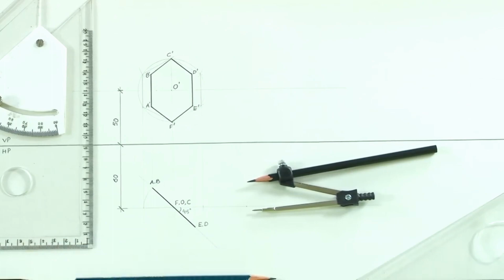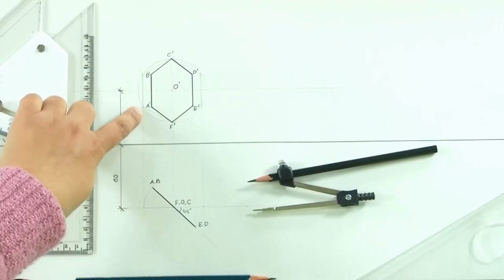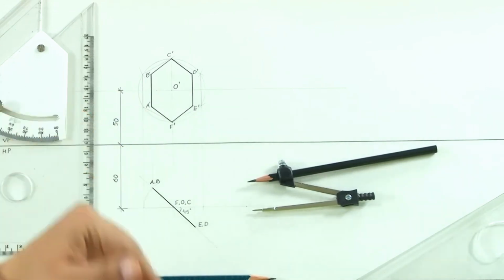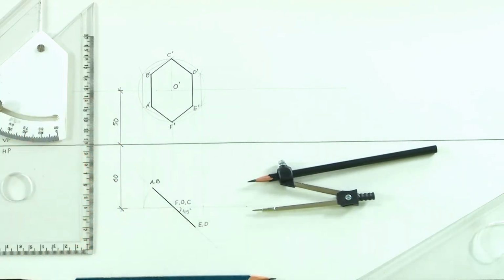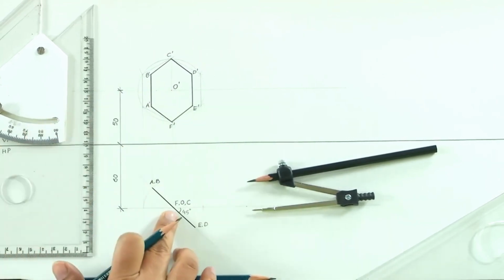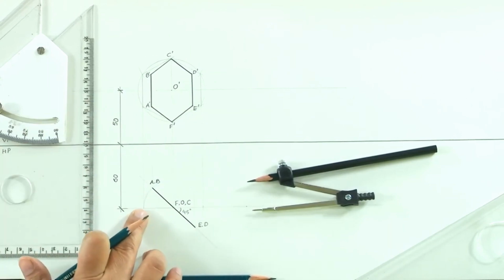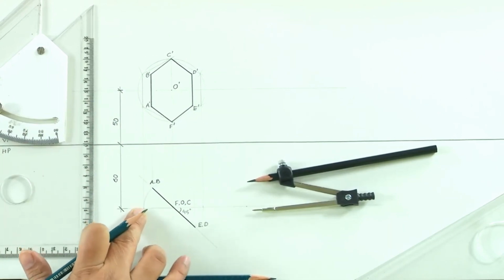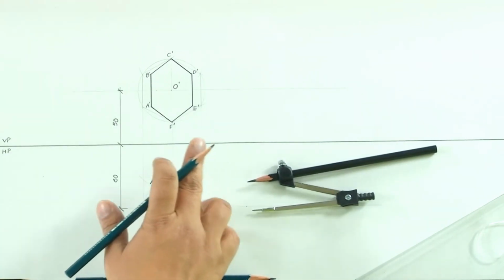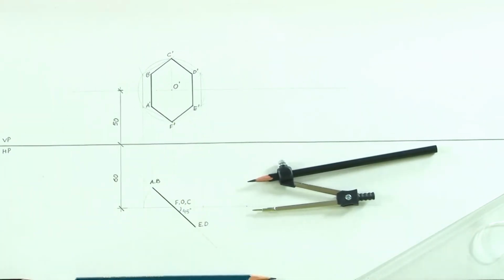Suppose we were given a condition where we were defining the side, saying that this side is at a distance of x and y from HP and VP respectively. In that case, we would not have tilted this plane about its center. We would have inclined this plane about one of its corners. So, that is how the change in the projections would come, but here this was to show how it would look. So, depending upon how the plane is being inclined, it will become skewed.